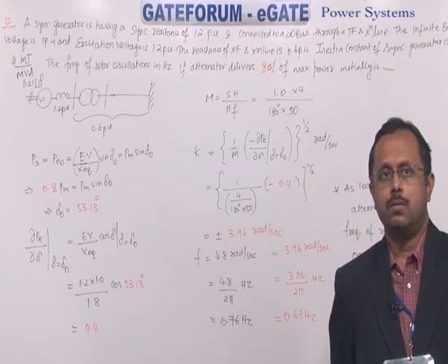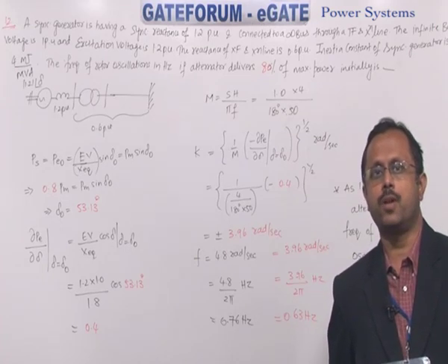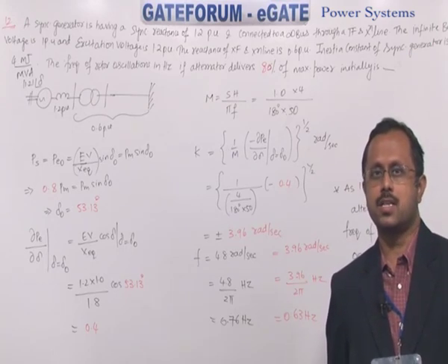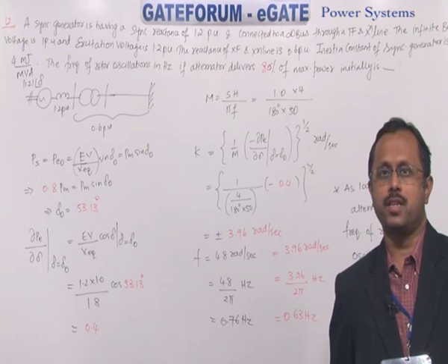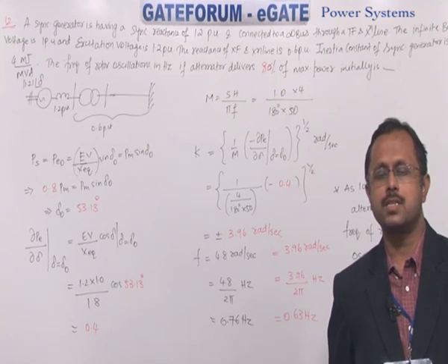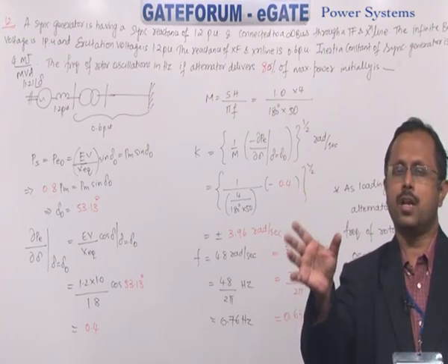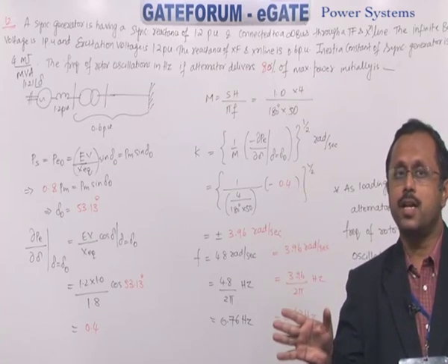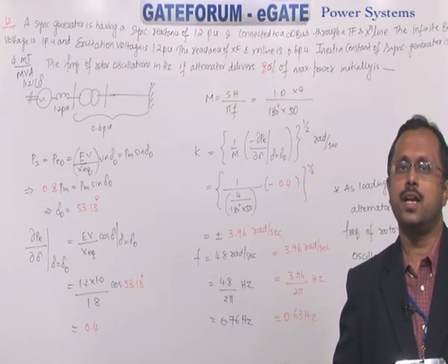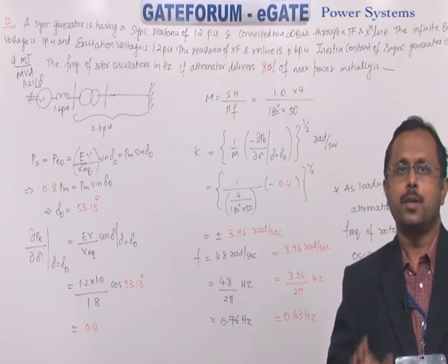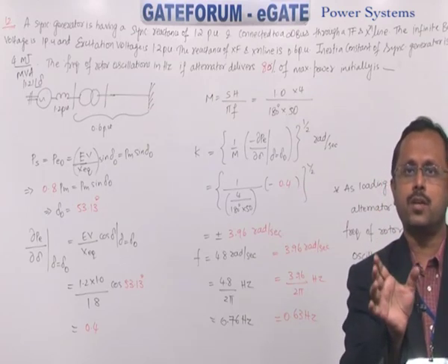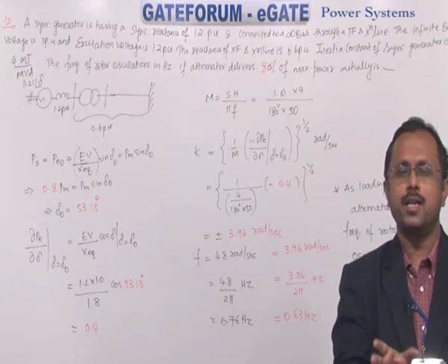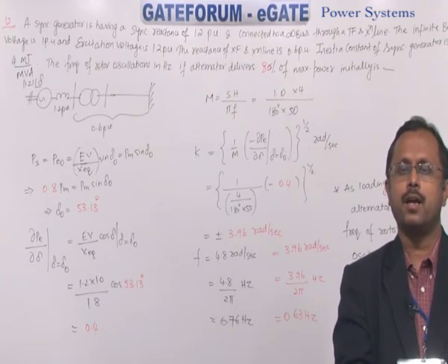Next question is by Vishwam from Agartala. How does the stator axis remain constant with respect to the reference axis always? For any change in the load, only the position of rotor with respect to stator changes, that is delta changes, but the position of stator with respect to reference axis gamma is not affected by the change in the load demand.